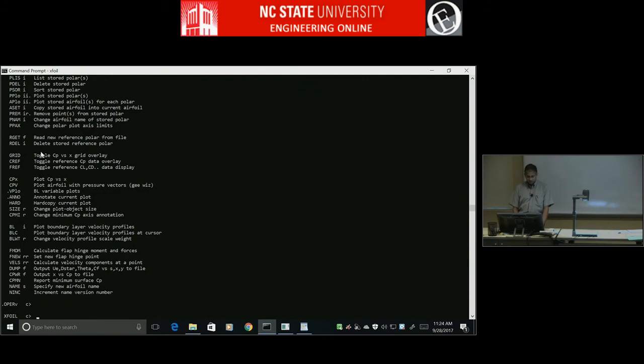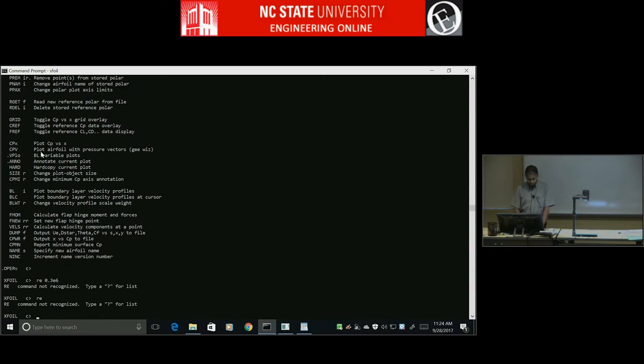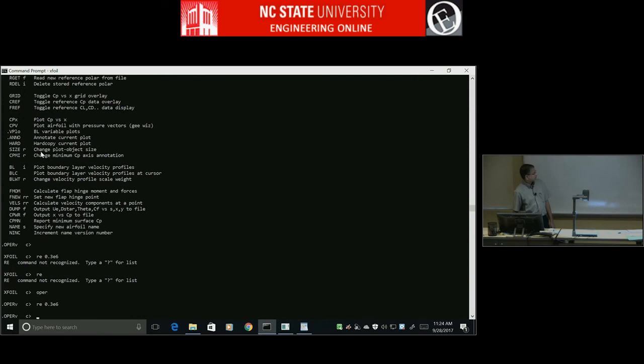So we're already in viscous mode. We want to change the Reynolds number, and let's make it 300,000. So 0.3 million. 0.3 E6. Okay, Reynolds number not recognized. Oh, I'm not in the upper menu. Somehow I went out. So Reynolds number 0.3 E6. Okay, I think it changed it.